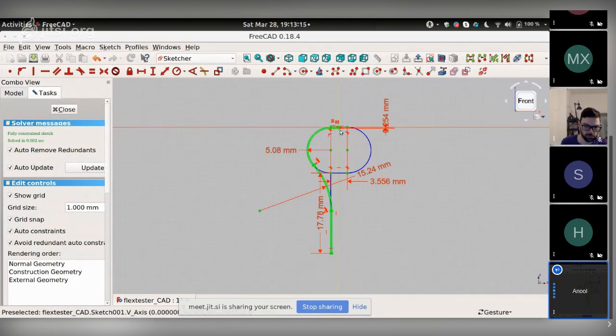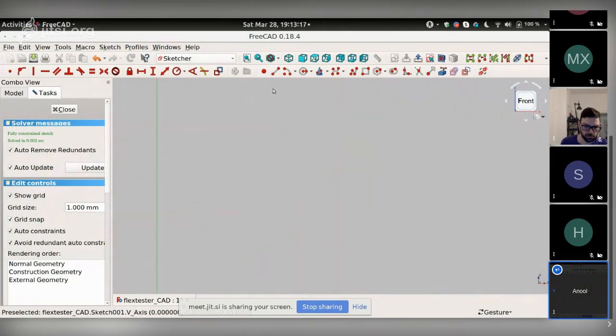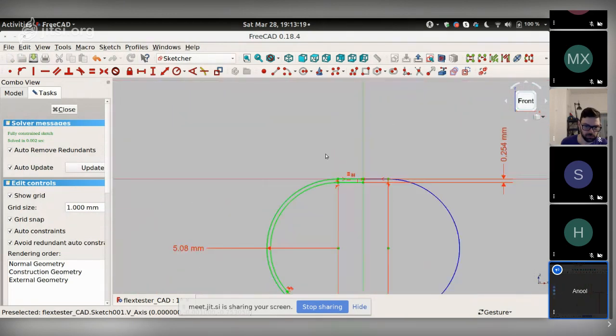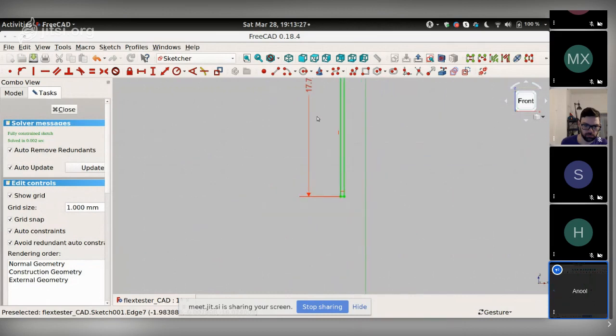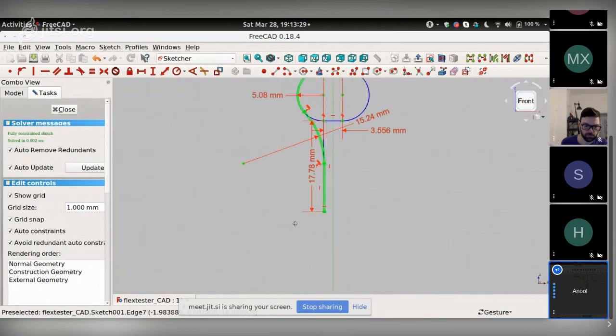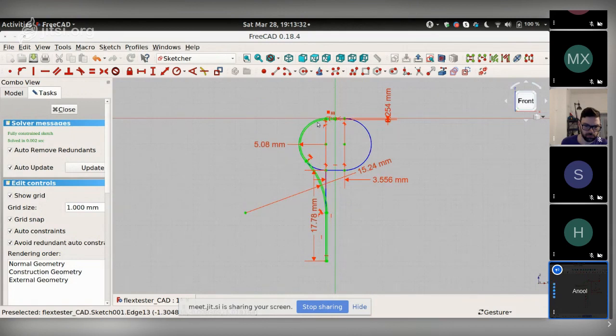So I figured out that I have a flat length of PCB over here, then a circular arc, another circular arc, and a straight part, all of it adding up to approximately the length of the PCB. Well, half of it, because I'm just mirroring everything later on. So these numbers are guesstimates. Maybe if I use the sheet metal bench, this could actually have been much more accurate in hindsight.